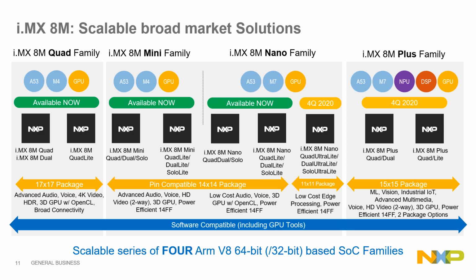The 14 nanometer FinFET choice for the Mini and the Nano enables pin-to-pin compatibility, but also faster operational speeds for the core complex of A53s at lower power consumption. This power efficiency and performance is only one of the key features that we present with the Mini.